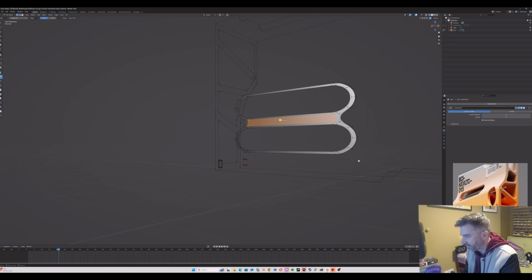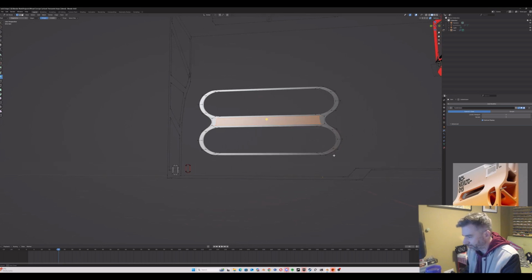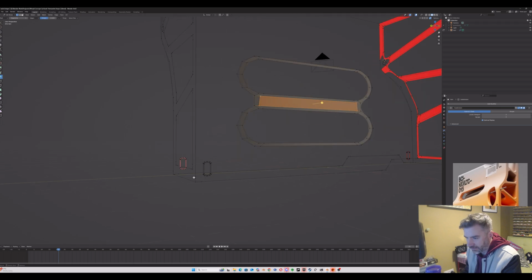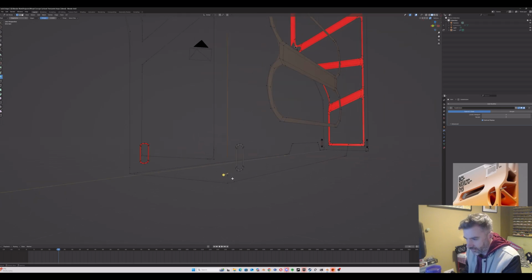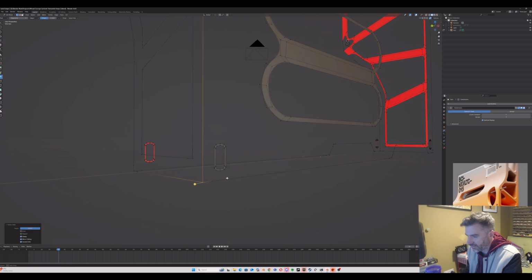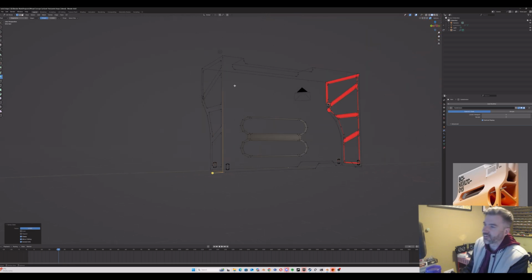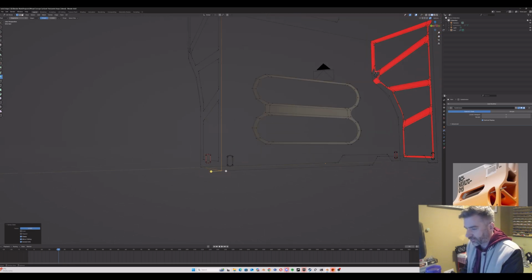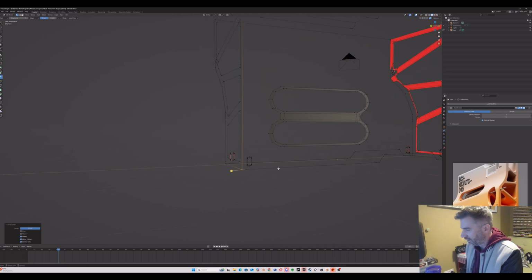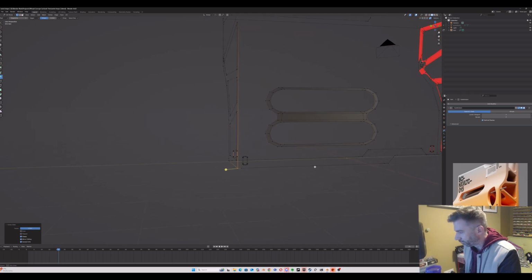And now we have, how do we want to do this? I don't think I want to join this to this. I don't think that makes sense. I've got 2 vertices here and I don't know why. So let's get rid of these. So we could just slide them down. And as long as you've got this turned on, they'll disappear. So let's take these out for now. I think we needed these to start with because this line wasn't anchored to anything, so it was curved.